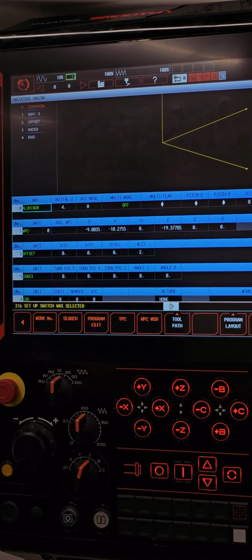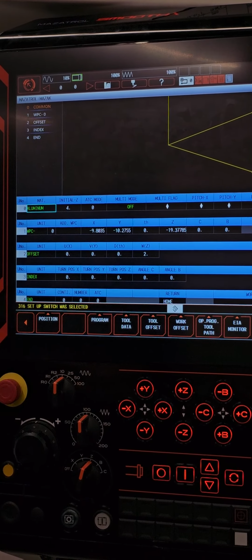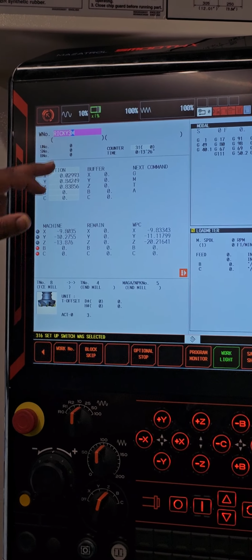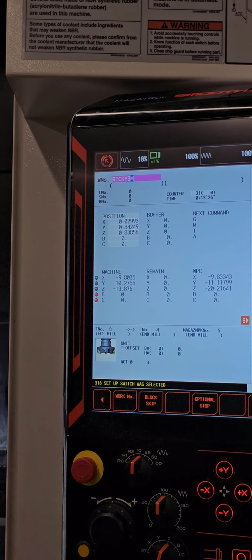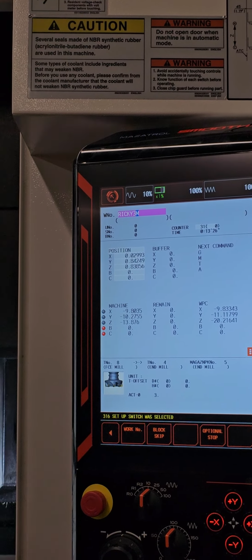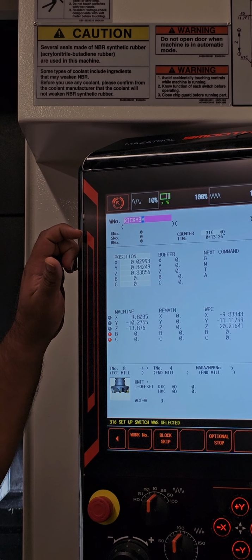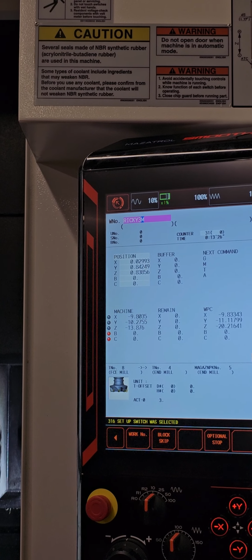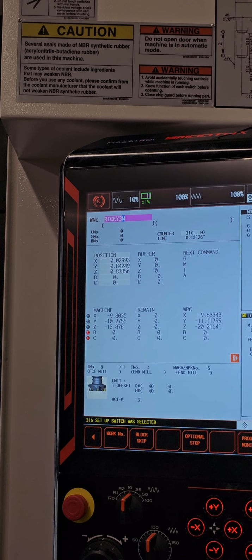But now over here, my program name is Mazak, right? You still gotta come over here, and if you see that, that still says Ricky 3. So even though I made the program, I have to make sure that I transfer it over here. Because if I don't do that, I'm not running my program. So if you don't do that on your test, minus 50.